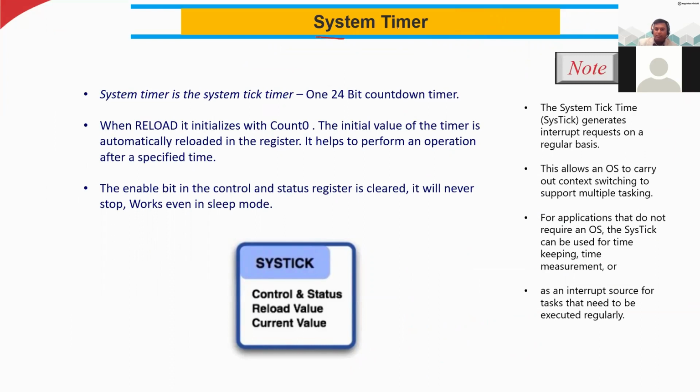And we have the system timer. It's actually the system tick timer. It's called SysTick. You will see this keyword if you look at the manual. SysTick means it's a system tick timer. So it has only one 24-bit countdown timer in this case.